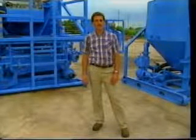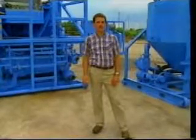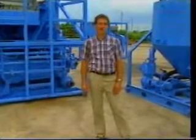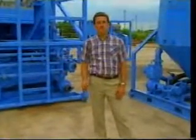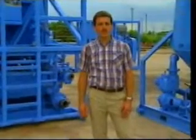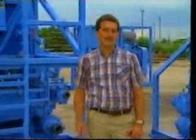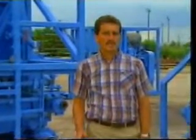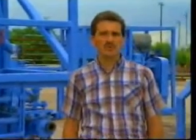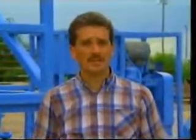Sand control is both a completion and workover technique that is necessary in many of the more prolific reservoirs throughout the world. It must be emphasized that due to the natural high productivity of these wells, the primary objective of sand control is to prevent sand production, not to stimulate the well. The engineer does, of course, want to maximize production, and this can be achieved by exercising strict quality control measures and selecting the optimum sand control method based on careful testing and experience.